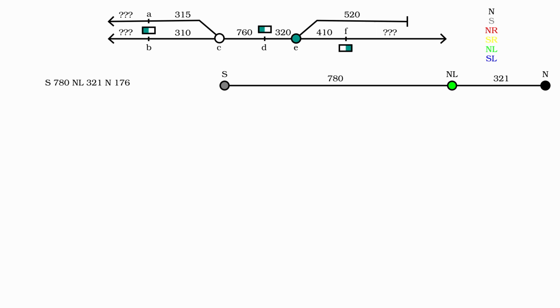We are going to check all fixed locations for a matching pattern. We have no information about the previous magnets for the fixed locations named A and B, so we will not check them. First out is therefore fixed location named C. When traveling toward the right, the train might have come from 2 locations, A and B. From the engine driver's perspective, the first magnet would have been a north pole on the right side when coming from location A, while it would have been a north pole on the left side when coming from location B.